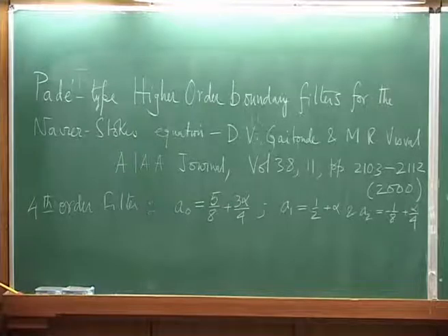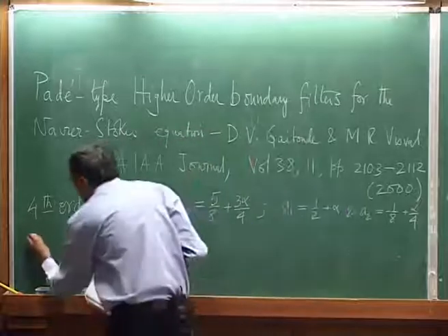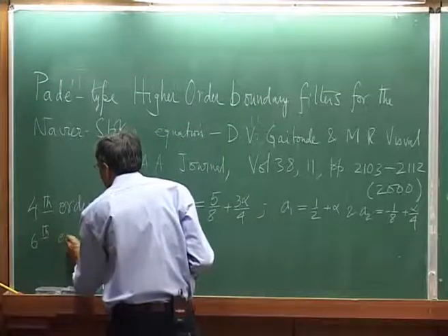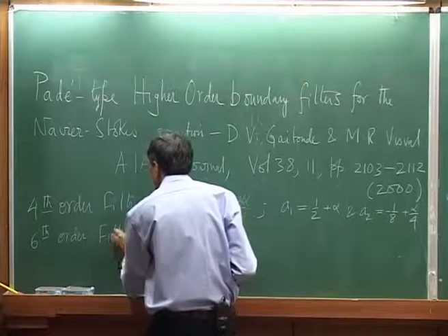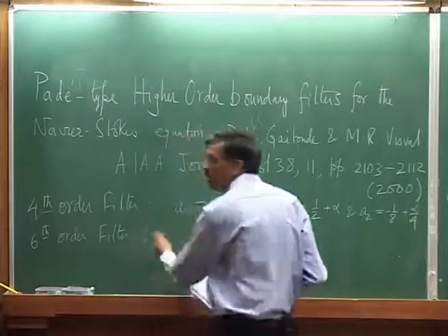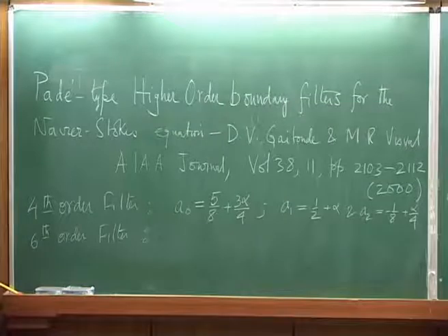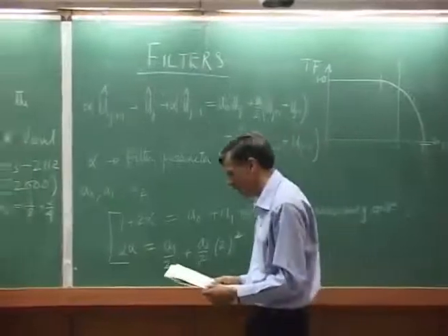and we have also seen the fourth order filter behavior. And you notice that the coupling of the terms on the left hand side and on the right hand side ensures that the order of the filter always increases by 2 by adding one set of extra terms on the right hand side, right. That is what we have done here. The moment we have added this A2 term, we have gone from second to fourth order, right, and those are the coefficients that you get.